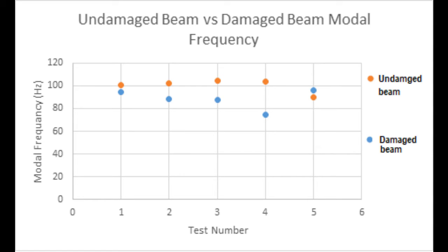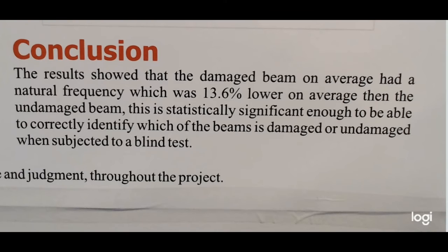The decreasing accuracy of each subsequent test might be down to 2 main factors: the heat of the motor not being able to dissipate quickly enough between tests, and the bolts holding the fittings and fixtures on the supports together shaking themselves loose. In my conclusion, detecting damage with sound definitely has some promise, but there's a lot of work that needs to be done to improve the accuracy.